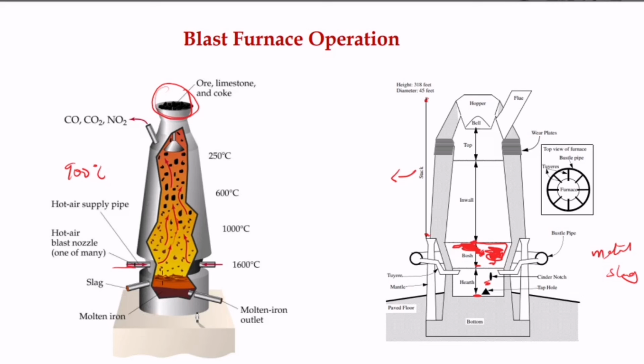the heat generated there melts the iron. The resulting molten metal, or the hot metal, is tapped at regular intervals by opening the what? The tap hole in the bottom of the furnace so that it can flow out. The flux combines with the impurities, the coke and the ore to form what? The slag, which floats on what? Which floats on the surface of it.